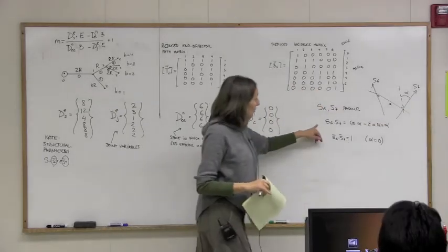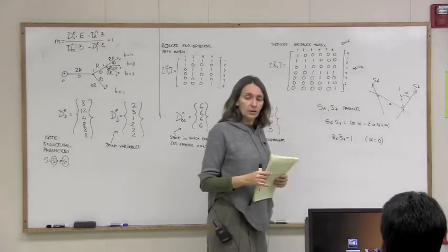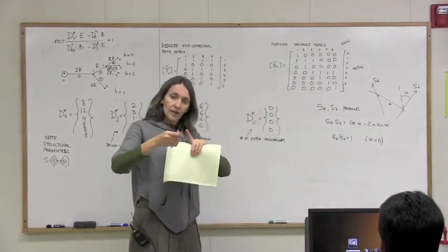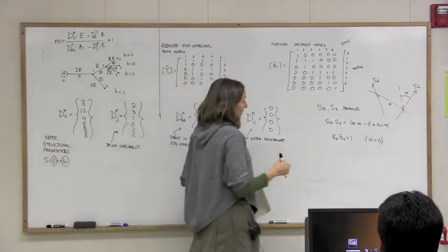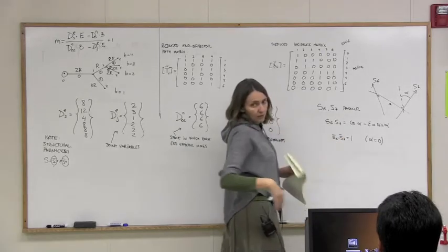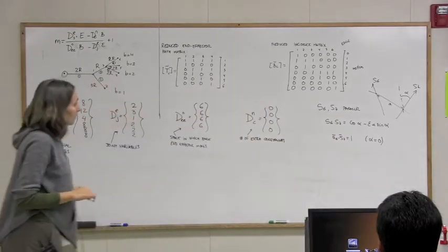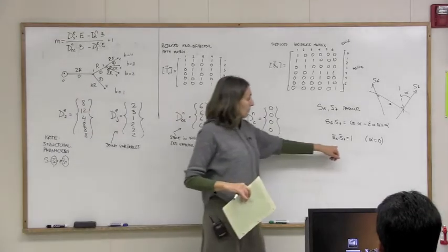So using the dual dot product and the dual cross product, you can impose conditions on relative location and on the angle between lines very easily. And these are unit vectors, so that means alpha equals 0 or alpha equal to pi, which is also acceptable, right? So you will have this extra bilinear equation.